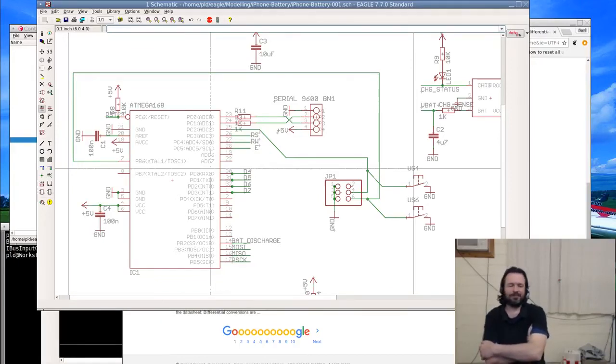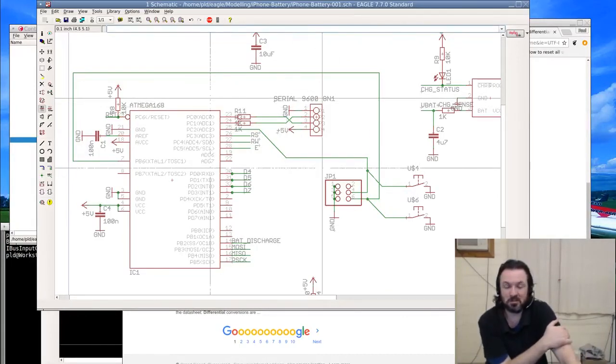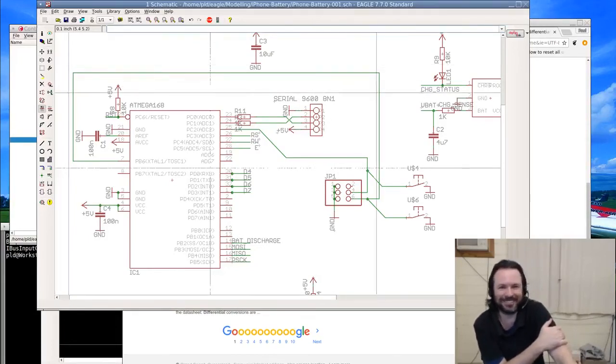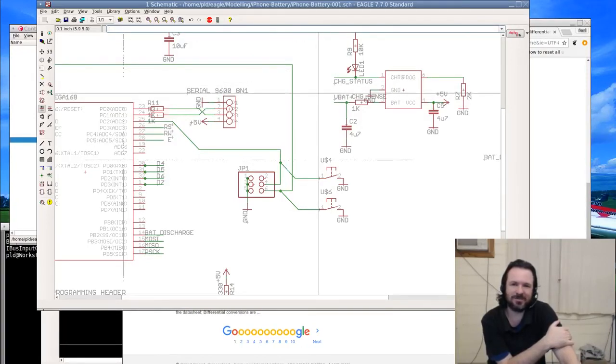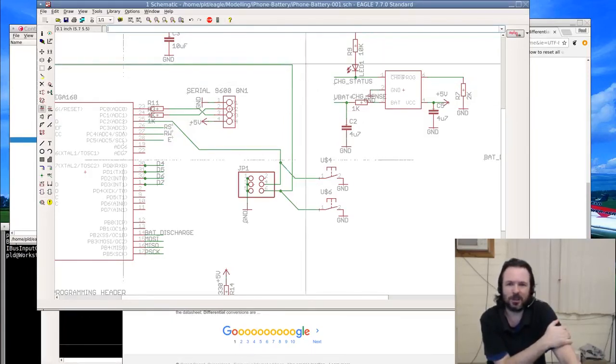When you design things, you tend to, I wouldn't say you get a hatred for some things, but you find you just don't have a lot of luck with a particular design option. And for me, op amps have always given me more grief than what I've gained from them. Oh, there you go, Spencer agrees. That means everything must be right. Because if I want to get an op amp up on the high side, I'm going to need a rail-to-rail, and they start also behaving weird up the top of the rail. Mind you, I will be running this off 5 volt.